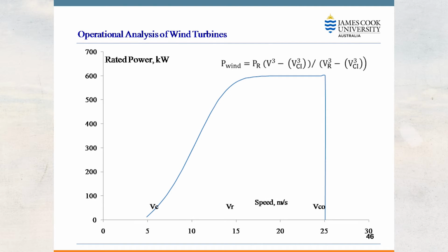These are the 2 factors that we have to consider in order to compare and choose a good wind turbine. When you visit one of the wind turbine manufacturers, they give you a curve, which they call the power curve. As I said before, these are 3 important wind speeds. Anything below cut-in is not useful, so the wind turbine will be locked, not working. Anything above the cut-off wind speed is also not working, to avoid damage to the wind turbine, but the operating point